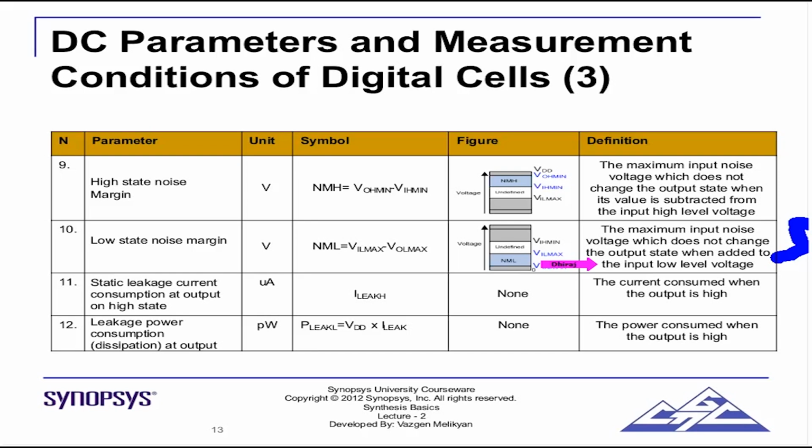But now it is a very important part of our implementation because the technology has been changing. We pack so many gates in a certain area. So noise is a real factor, a big danger now. But still, as far as synthesis is concerned, we do not need to worry about these values. They will come when we start the subject of static timing analysis. So it is only an effect after place and route is done, not before. So synthesis does not take into account any noise.